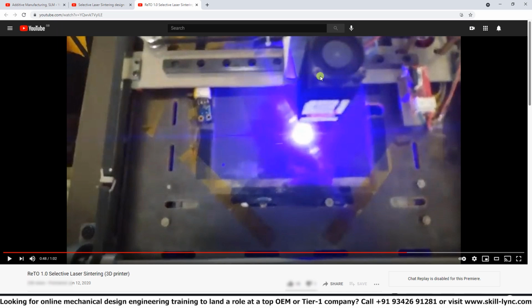Again, in the horizontal plane, but along the Y axis. So the laser over here has 2 degrees of freedom, along the x-axis and along the y-axis, and the third degree of freedom is provided by the build plate in the vertical or z-axis. So in total you have 3 degrees of freedom, and these 3 degrees of freedom are present in all of these additive manufacturing technologies, right?